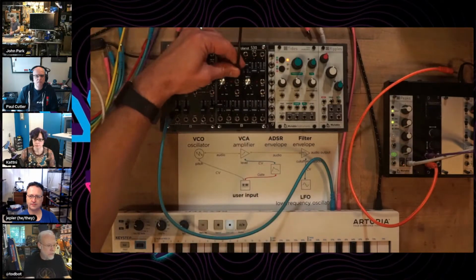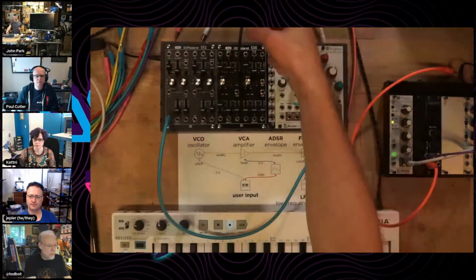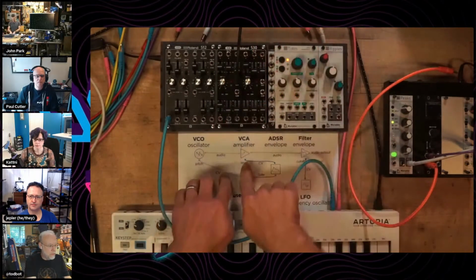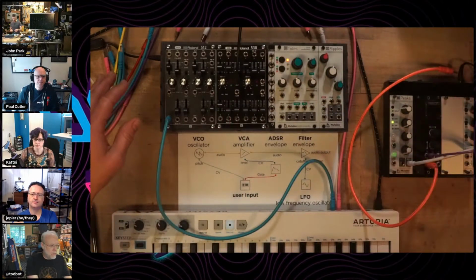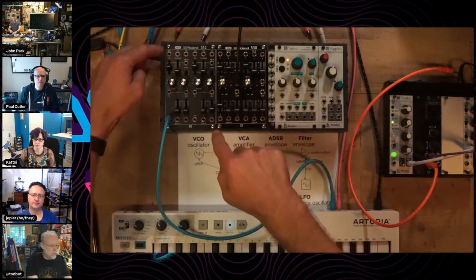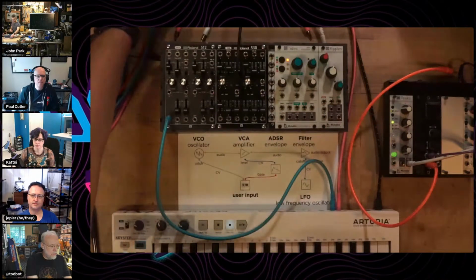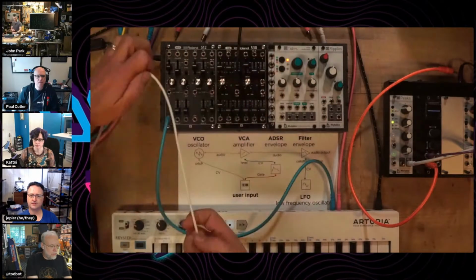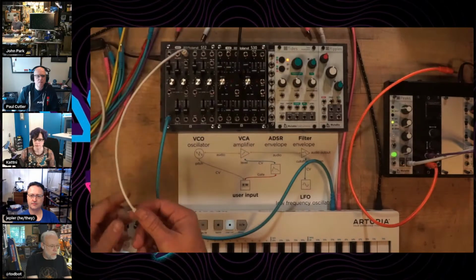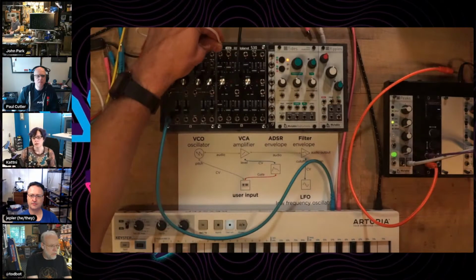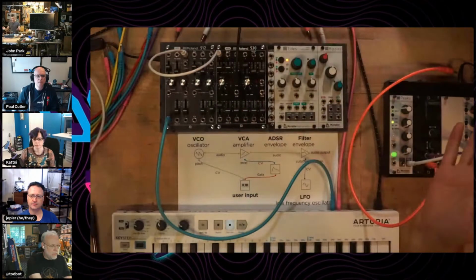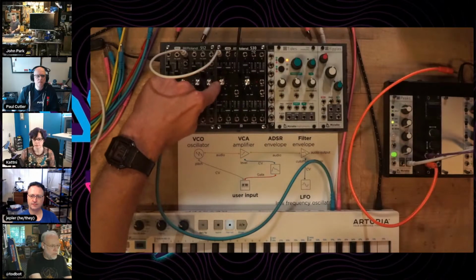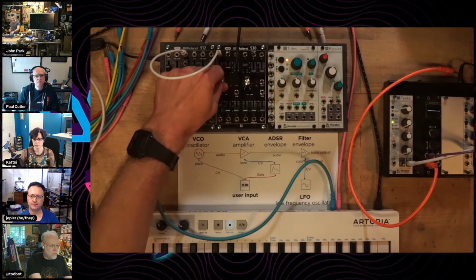So what I'm going to do is send my output from the VCA to my little amplifier, my little speaker, I should call it over here. And now I'm going to patch what's coming out of, what color did I use? I think white. What's coming out of that VCO, there's that saw wave again, and that's going to be an input signal going into the VCA. You don't hear anything, and that's because I have a volume or level knob that's at 0.